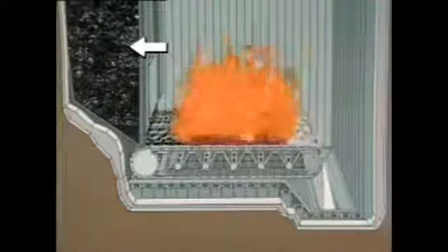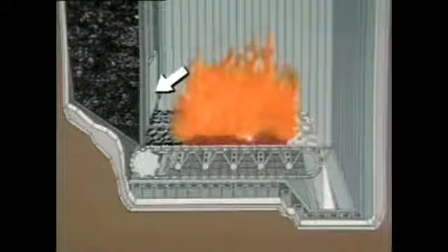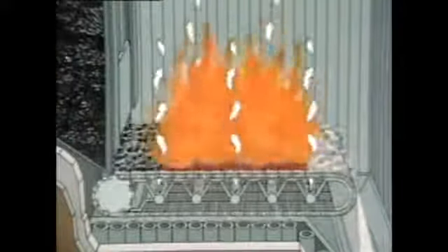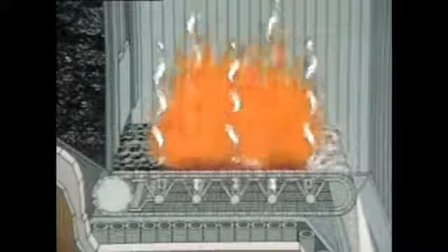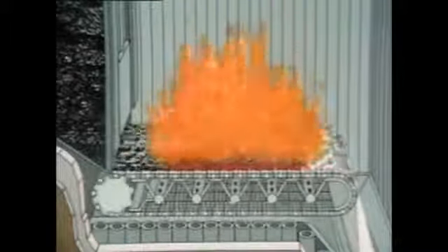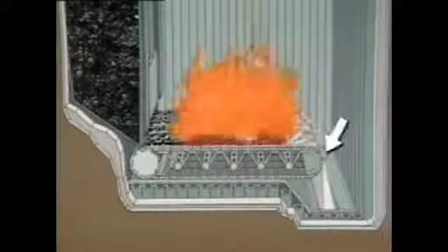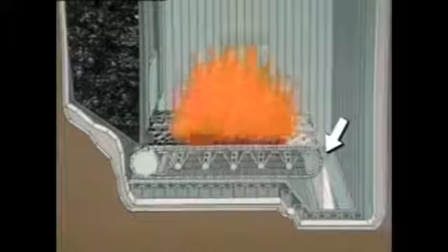The coal is stored in a hopper. A gate controls the amount of coal fed to the grates. As the coal moves along, air is forced up through the grates to provide the oxygen needed for combustion. The burning coal moves through the boiler's combustion area and supplies the heat needed to produce steam in the tubes surrounding the combustion area. Coal ash falls off the grates into an ash bin.